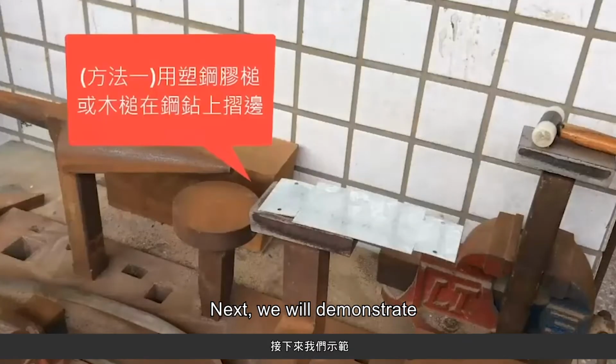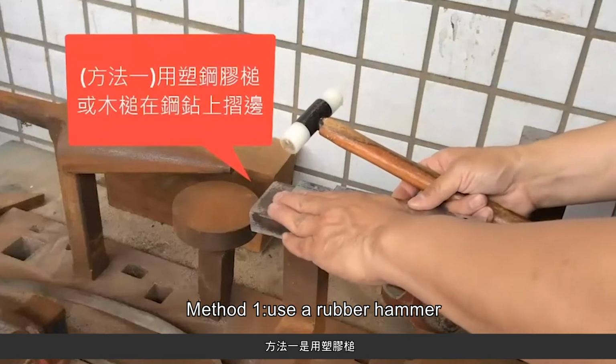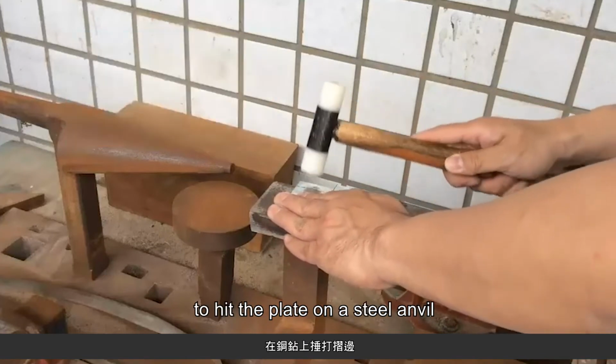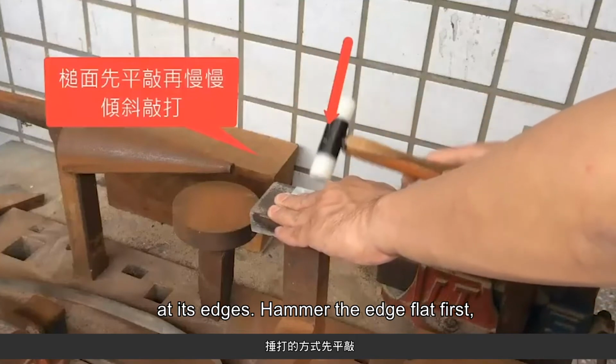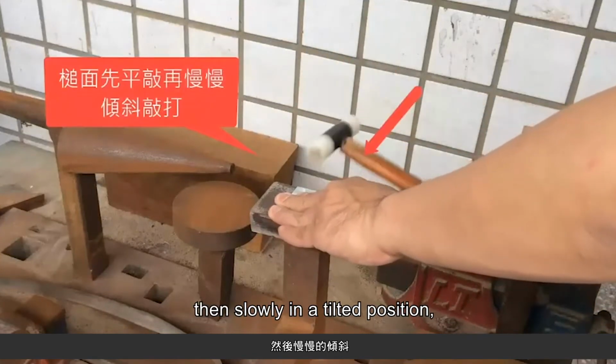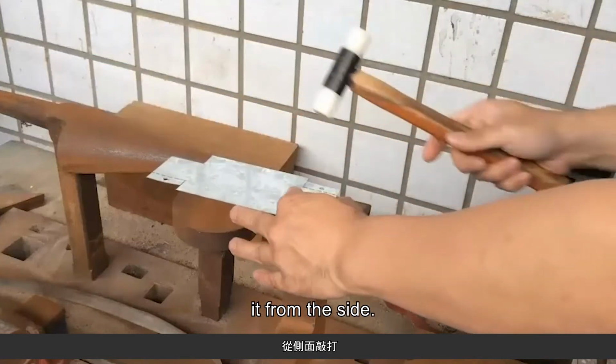Next, we will demonstrate 2 ways to hem the edge. Method 1. Use a rubber hammer to hit the plate on the steel anvil at its edges. Hammer the edge flat first, then slowly in a tilted position, and finally turn it to 90 degrees and hit it from the side.